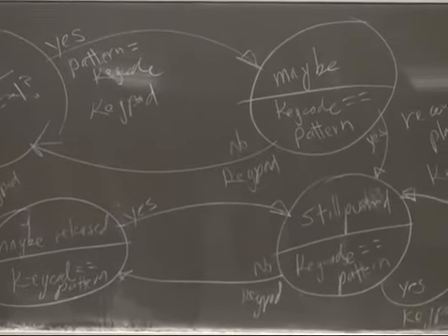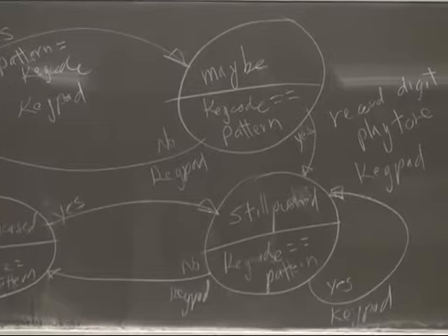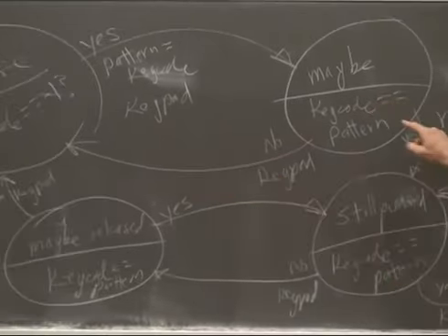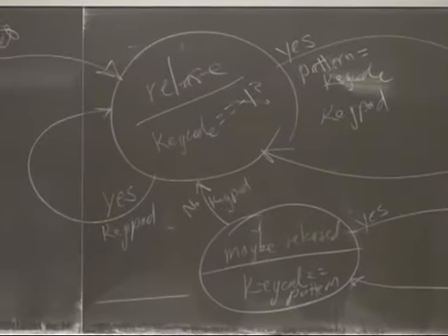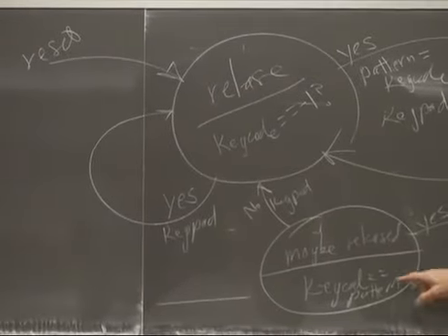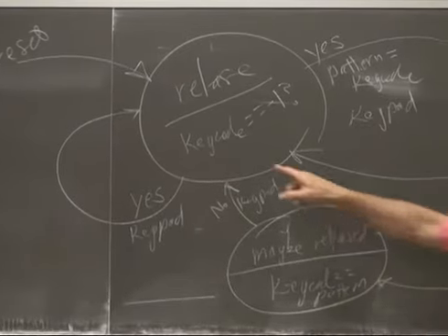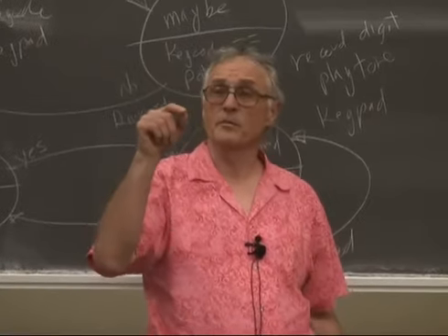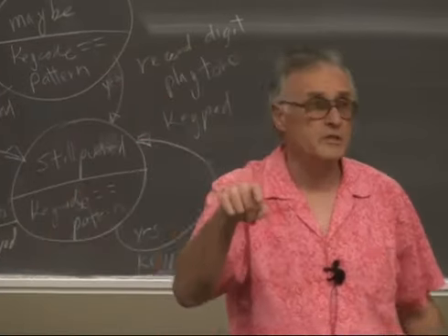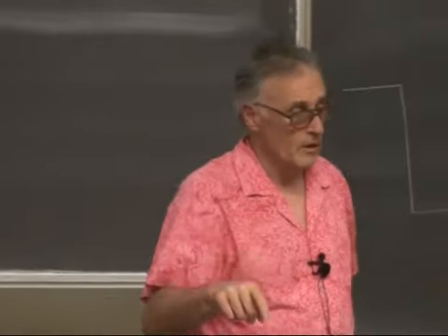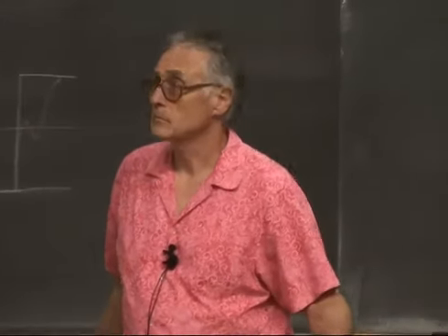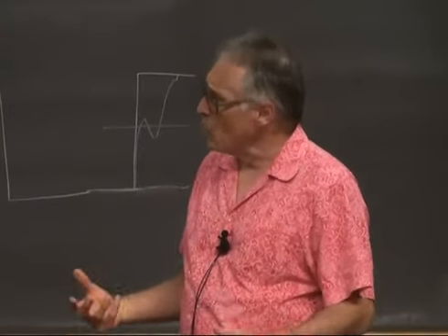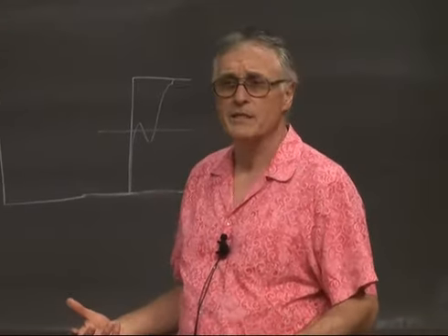So you're going to build a 4-state state machine. It's very safe. It's interlocked. Once you press and hold, then you have to unpress and not hold for 2 30-millisecond cycles before you can press again. So it's very safe in terms of producing bouncing multiple results on a single push, at the cost of a little bit of program complexity, but not much.